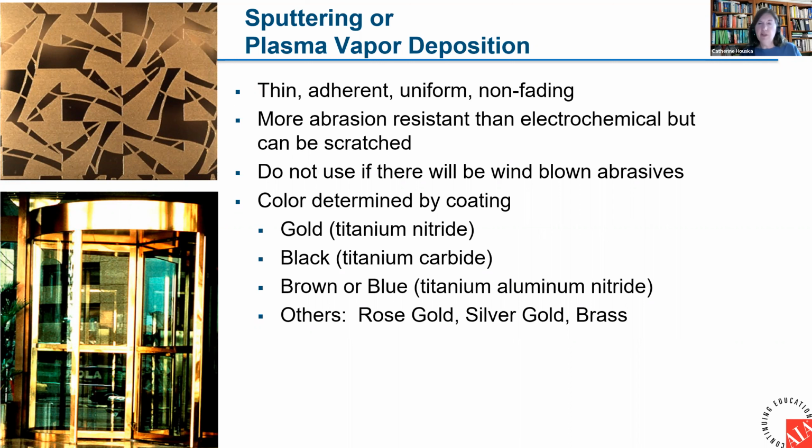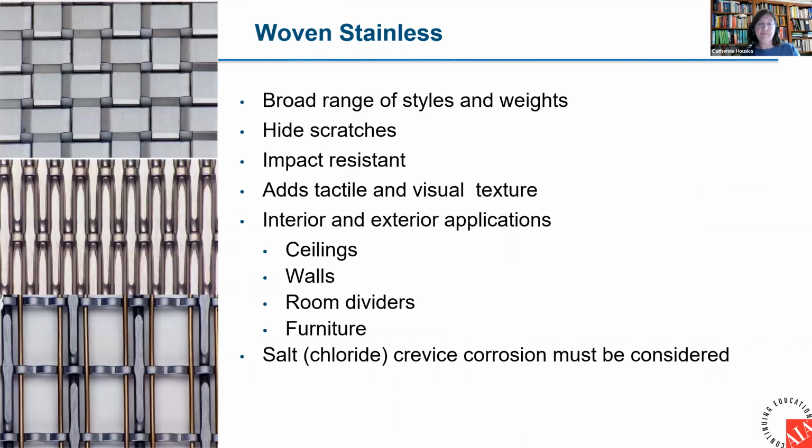Now, that was very carefully specified. I was involved in that project, but there are other project examples where the quality of the PVD was not particularly good, where there's been delamination fairly quickly. So you want to use a very good supplier. You want to make sure there's a titanium underlayment, and a variety of other things are done if it will be an exterior application. If you're not going through thermal cycling, then it is a bit easier to avoid issues.